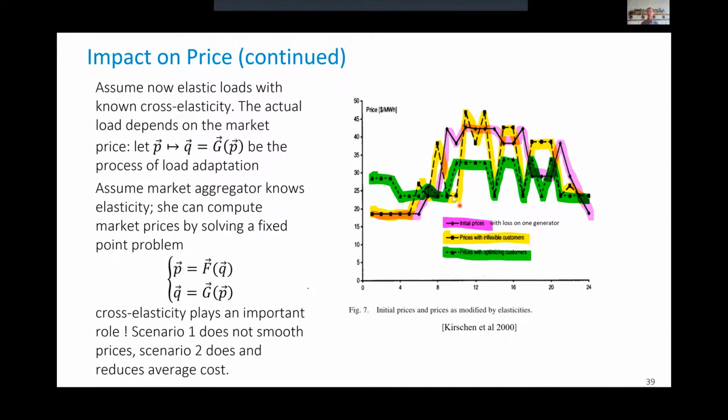The yellow one is the one where customers shift their loads in the 3 hours before or after uniformly. Then we see that truly when there is a peak in price here, that can be interpreted as a demand response effect. There is a surge before, that's the pre-bound effect, but we see also that there is very quickly a rebound effect after. In fact, during the demand response event, those loads are able to follow, but only for some amount of time. And in fact, we see that the peak price even gets worse. So the peak price is higher with demand response.